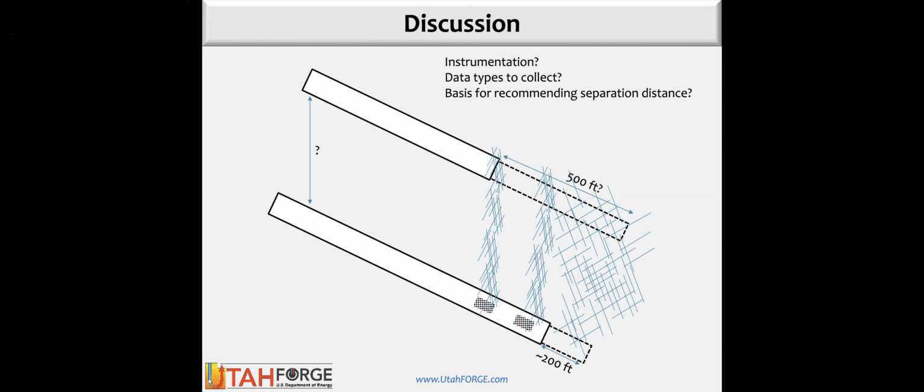Okay. Are we trying to produce from the cased portion of 16B? So not until it gets perforated. I think we're not going to produce fluid through a 1/4 inch or 1/2 inch thick steel pipe. But eventually, Luke, yes, there will be plans for additional stimulations. I wish I could edit this slide, but we will have more stimulations that will happen in A or perhaps in B, and wherever we see, based on the measurements, where they encounter that well, we can come back through and perf after the fact to try to connect them there.